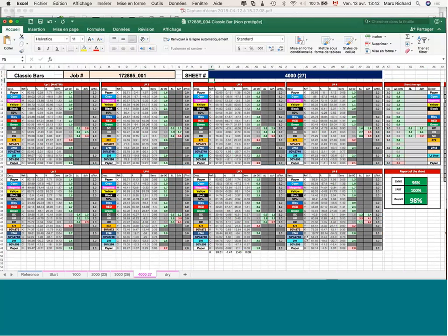called SpectroDance Connect. And once we put the instrument over the strip, and we press and hold the button, and then we scan from left to right or right to left, that's what captures the data from the strip. And then that gets copied through the clipboard over into that Excel sheet. And we repeat the operation for all 8 positions that we are inspecting. And on the right-hand side, we tabulate the totals. And then we can calculate the statistics.